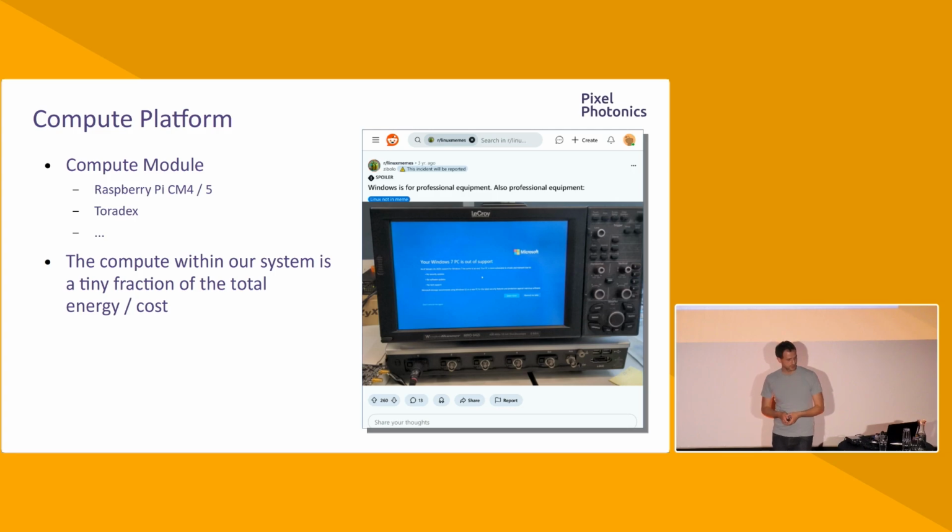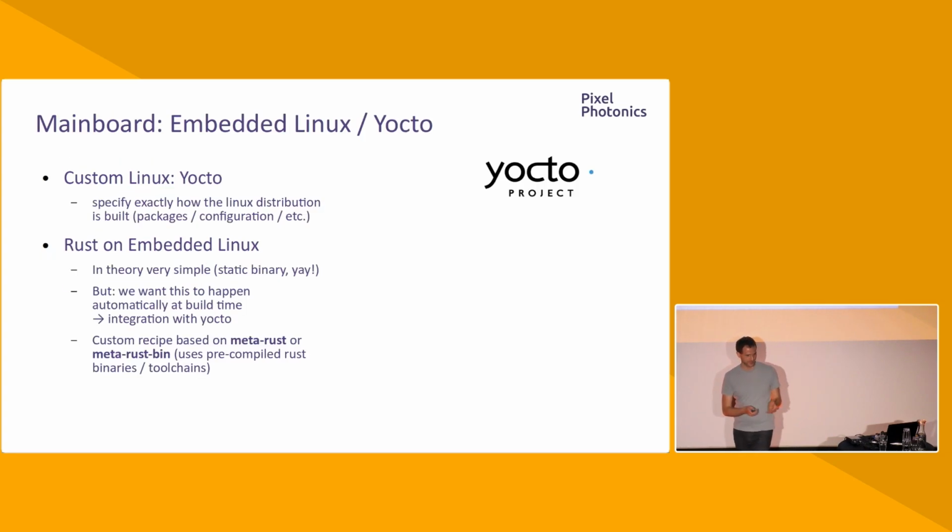So in our case, we didn't want to have our users greeted by blue screens. So we use Linux, and we actually use Yocto to build a custom Linux system for our device. For those of you that don't know Yocto, it's essentially a build system which you can use to configure a Linux distribution exactly to your needs. And this is, of course, very nice for the embedded use case.